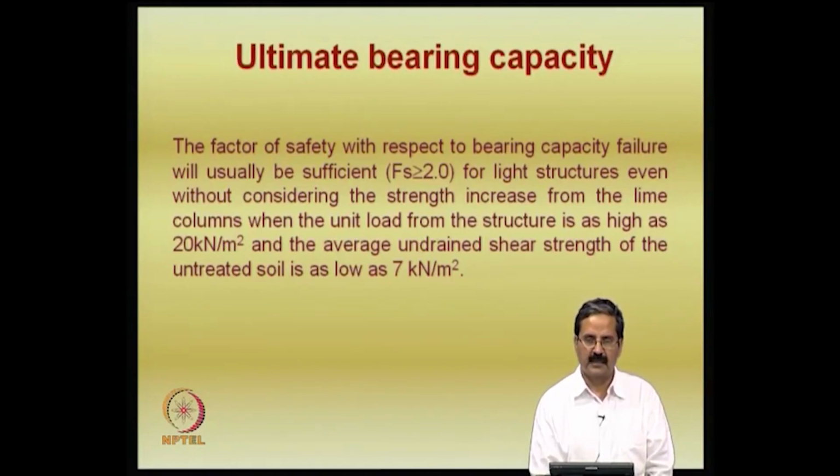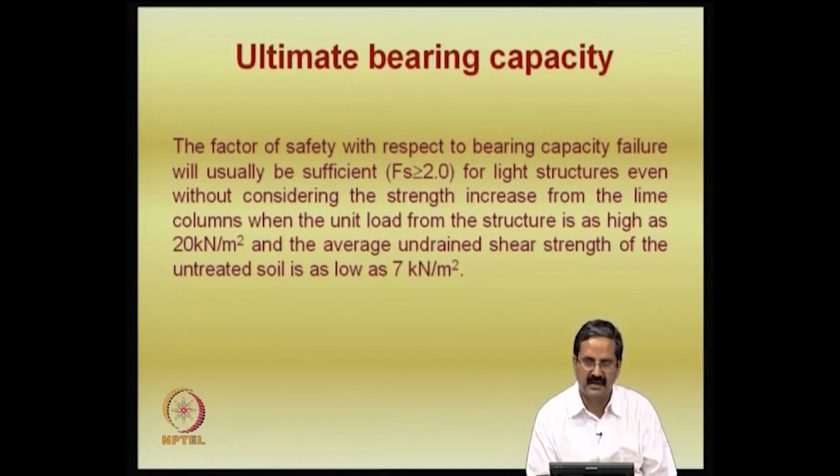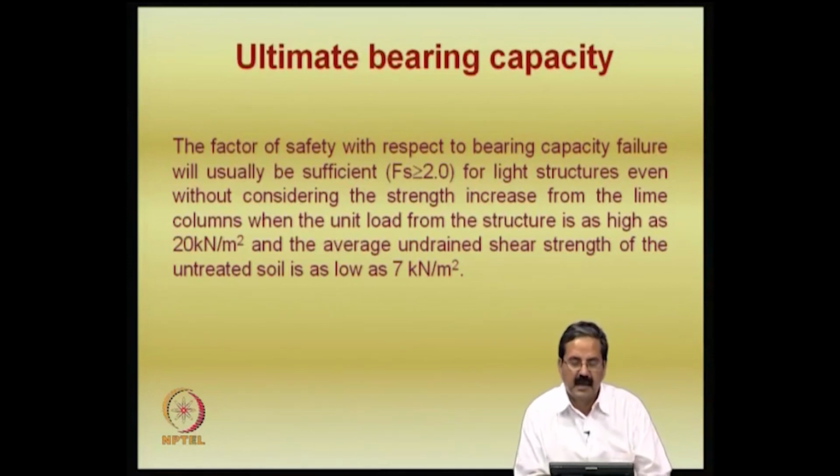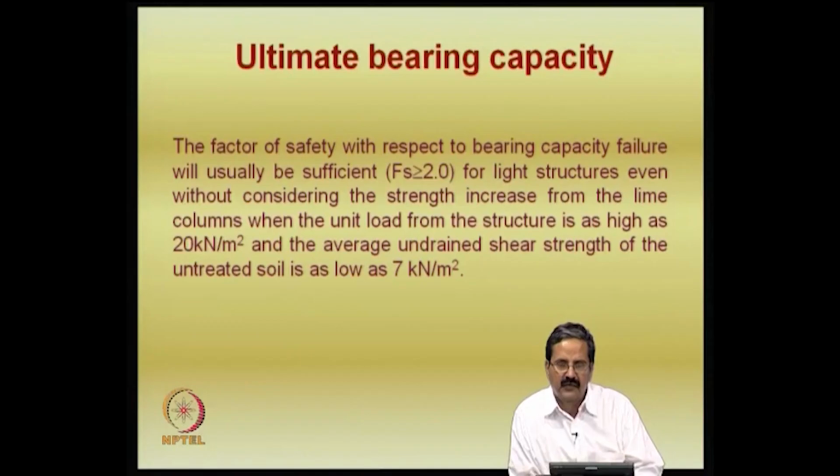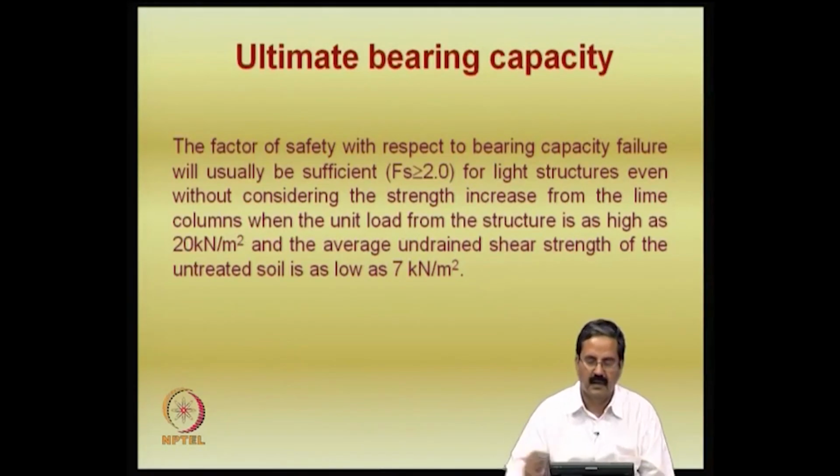Maybe Cu could be 10 kPa, and it got improved to 50 kPa because of the lime treatment. So, there is a 5 times increase in the ultimate bearing capacity. Even if you multiply by 5.14, the ratio being the same for both cases, the ultimate bearing capacity, instead of 50 kPa, could now be 250 kPa. So, the factor of safety could be about 2 or whatever. Factors of safety have certain sanctity here in our geotechnical engineering, though you may have different factors for different conditions.